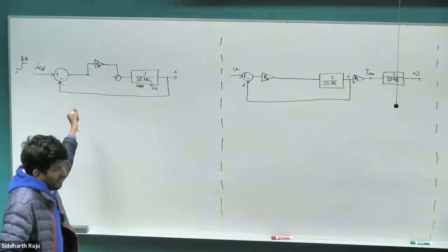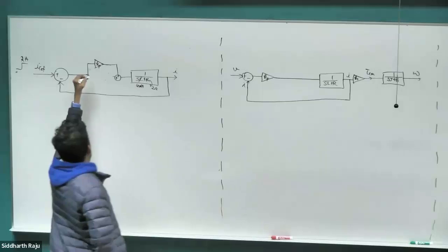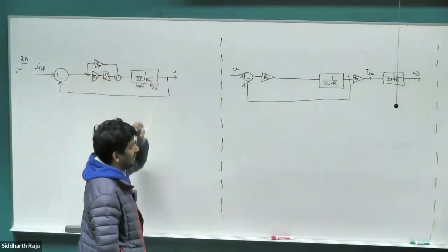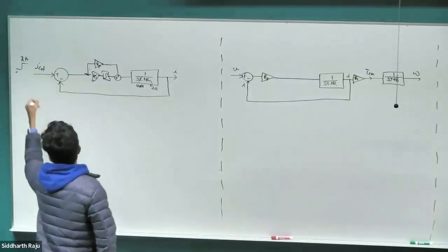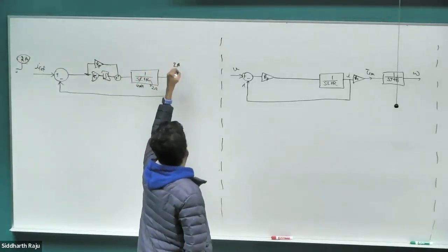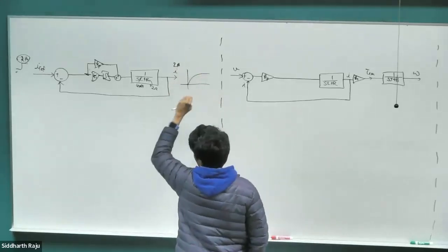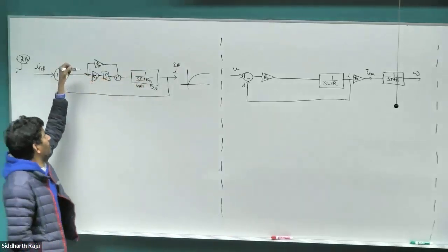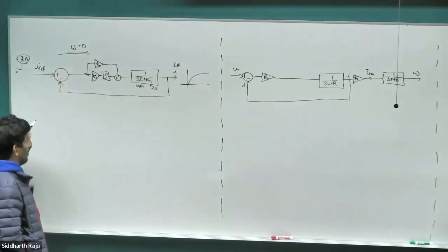So let's start with a simple one. Let's say there is the PI controller there. What will be the current at steady state? Same as IREF. So if there is an I controller, whatever 2 amperes I ask for here is going to be the same 2 amperes coming here at steady state. It will take some time to get there, and the time it takes depends on the control bandwidth, the omega C we chose for the inner current controller. Again, here we are assuming mechanical speed is 0, which is why the EMF term is missing.